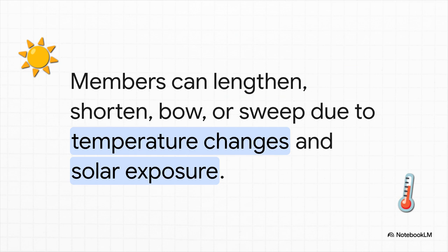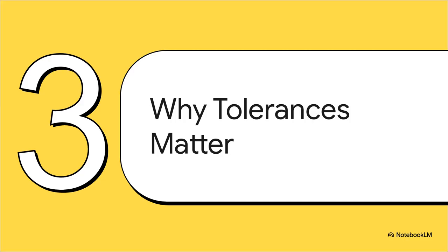And finally, never, ever underestimate temperature. A long concrete member sitting out in the yard with one side baking in the sun is going to have measurably different dimensions than the side that's in the shade. It can lengthen, shorten, bow, or sweep. It's a powerful force.